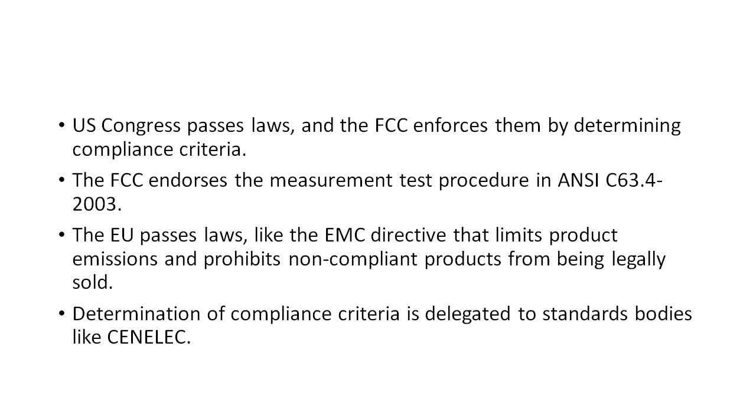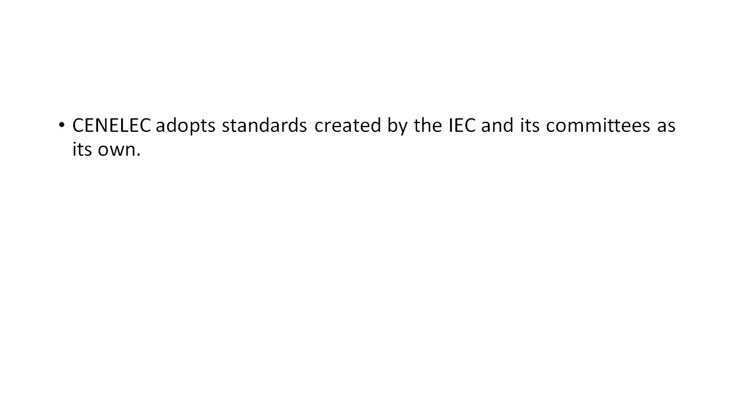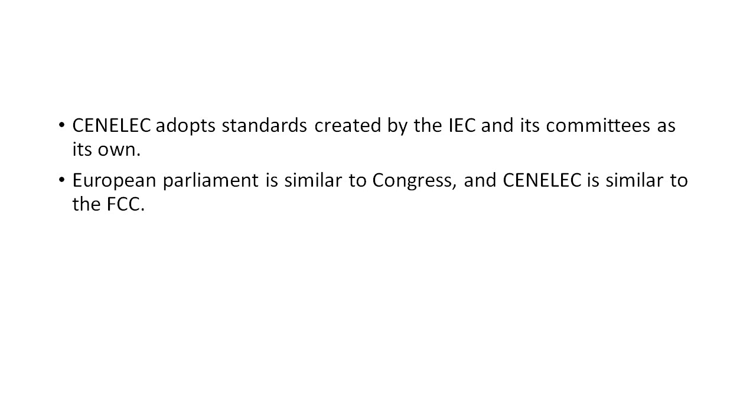So all that means in plain English is that the European Union bureaucrats delegate the actual technical standards writing to engineers and scientists employed by non-profit bodies like CENELEC. CENELEC in turn works with international organizations like the IEC and tends to adopt its standards as its own. CISPR 22 is an example of such an emission standard that contains both limits and measurement procedures. As I'll explain in a moment, it's been adopted by the European Union. So if you think of the European Parliament as being similar to Congress, CENELEC is somewhat similar to the FCC in terms of establishing what constitutes compliance with the law.